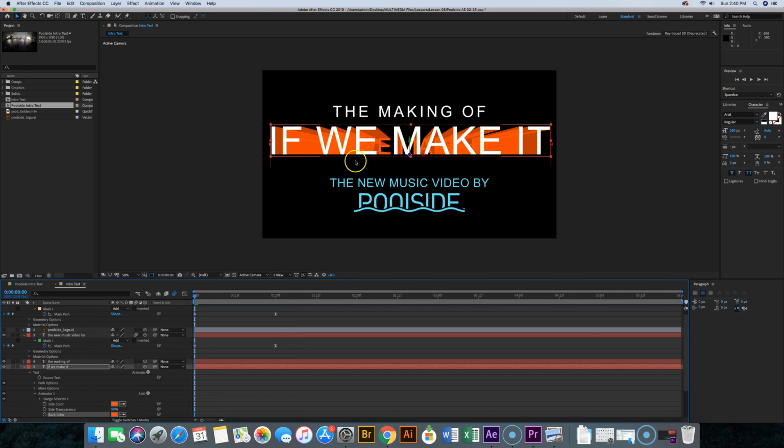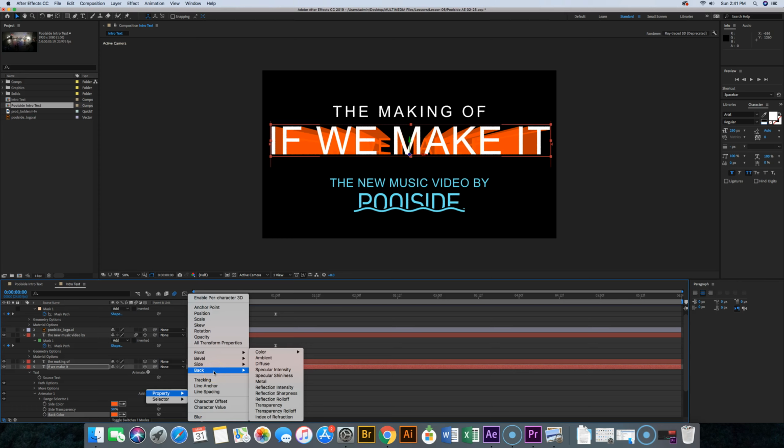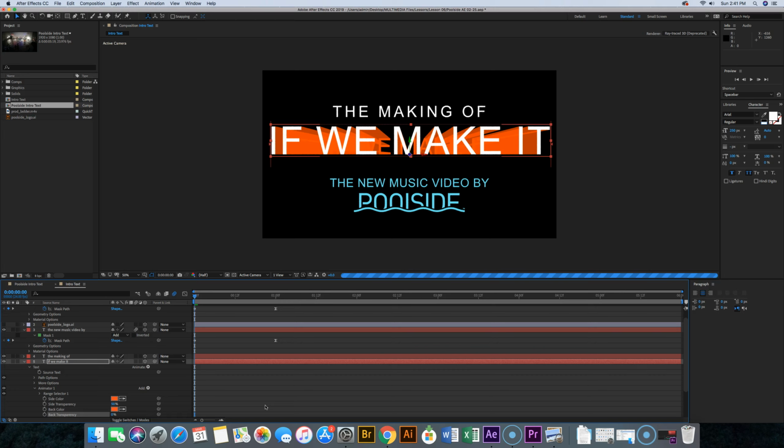And then you can see it's still perfectly opaque. We can't see through it at all. So we're going to hit the Add button one more time, and we're going to choose Property of the Back, and this time Transparency. And again on this one we're going to type in a transparency of 50%. So right here, 50%, enter. So we now have an extrusion. It starts back on the 0 point, and then in Z space it comes forward 2000 pixels, extrudes out towards us.